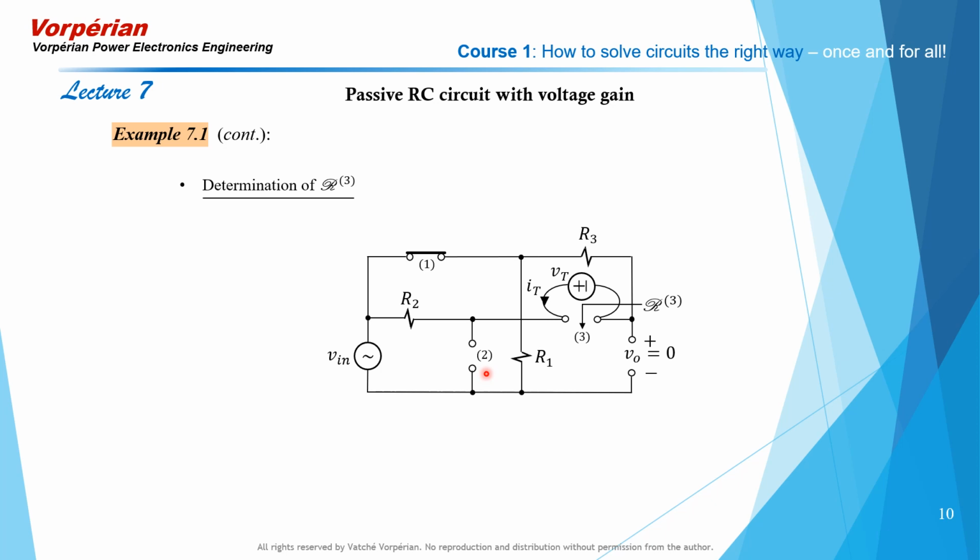You can see now that whether the response is null or not doesn't matter, simply because this part of the circuit, R3, R2, and Vt, form a loop entirely independent of the remaining part of the circuit, which is nothing more than R1 in shunt with Vin by virtue of port 1 being a short circuit.